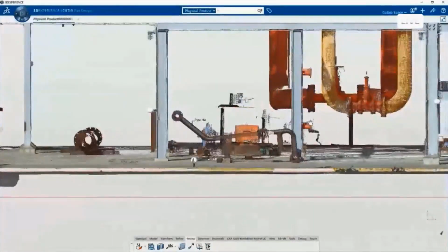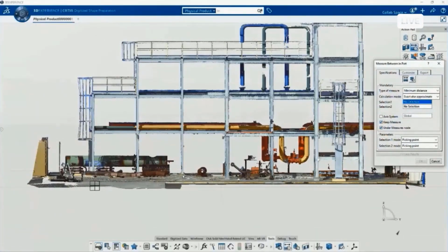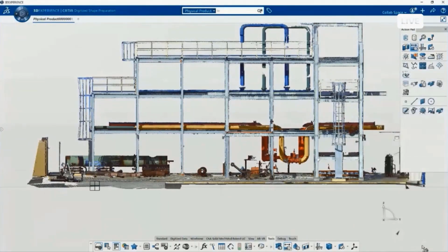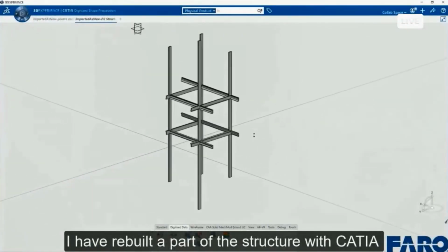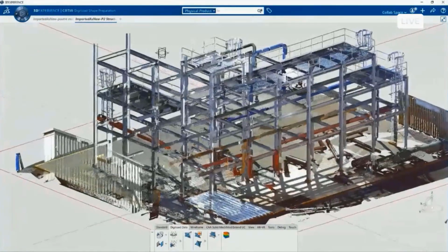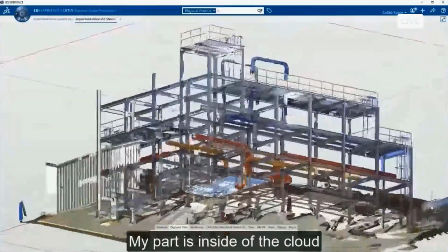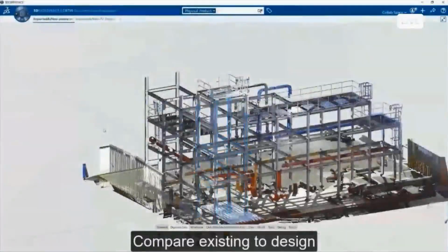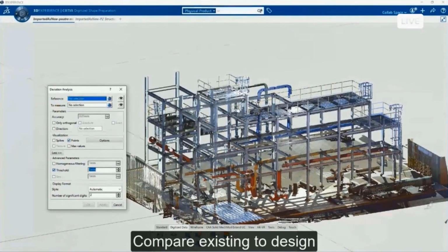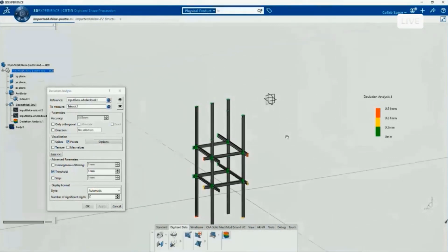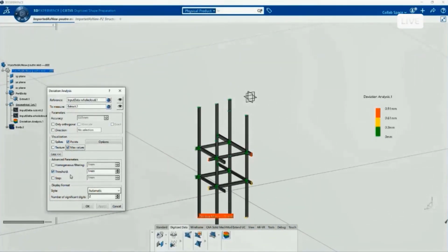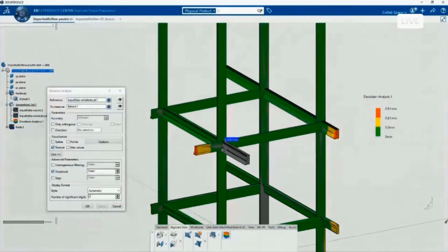Here we attach some 3D tags, for example, to isolate some entities, or you may want to compute distance between elements, maybe, for example, to check feasibility, to import a part inside, remove equipment, and so on. Or start some reconstruction process like here, reconnection of planes and cylinders, approximation of surfaces, like we saw earlier. And then you'll compare the existing CAD with the existing 3D model. So deviation analysis again, same tool as we saw, working here on 73 million points and some solids or surfaces, for example. See by color the deviation from the original.